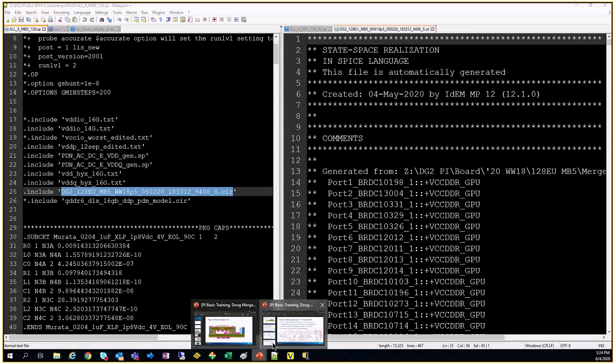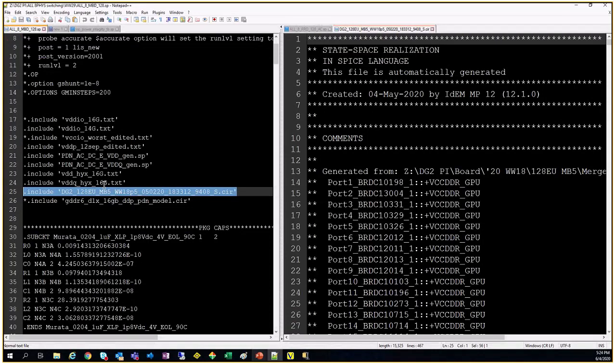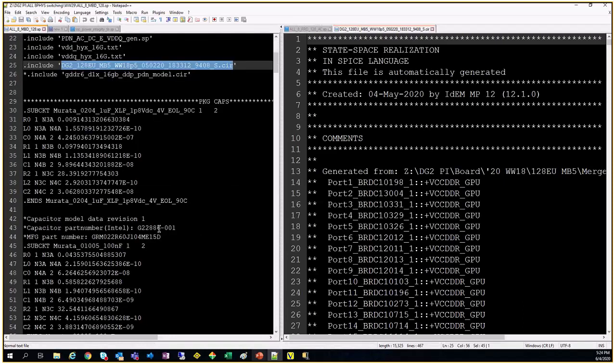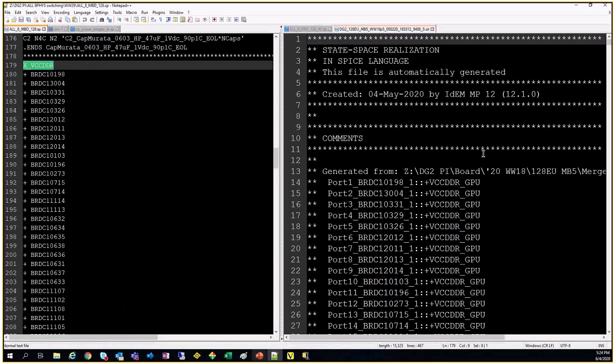This is how you first include it, like attaching it, to say that this file is going to be included as part of my main deck. It's in a separate file, but within the same folder. So this is how you use .include. You write the file name, and then you come down. I will explain these definitions to you. Then you start with X because it's a circuit, so you start with X, subcircuit file, X underscore some name.